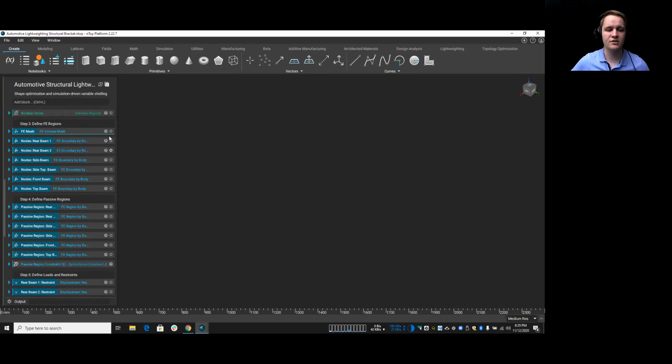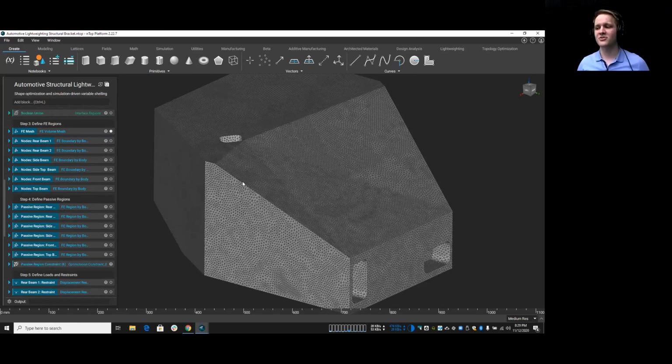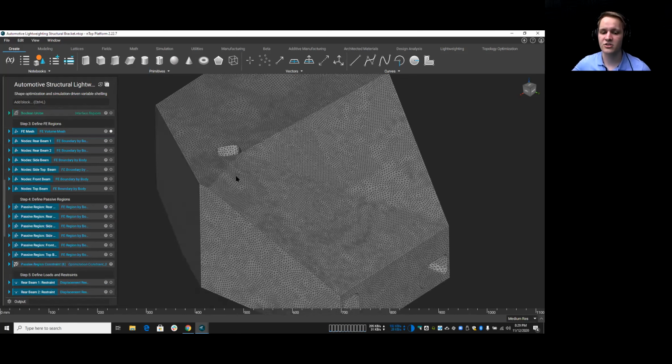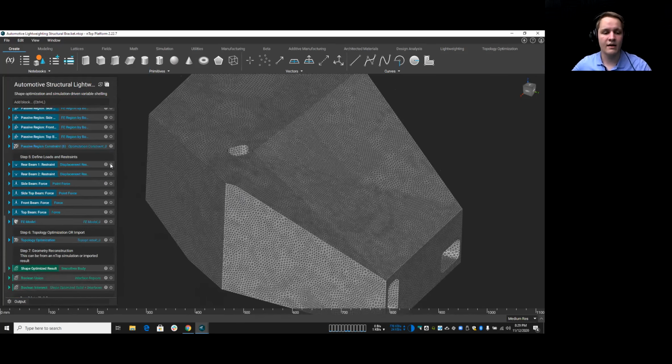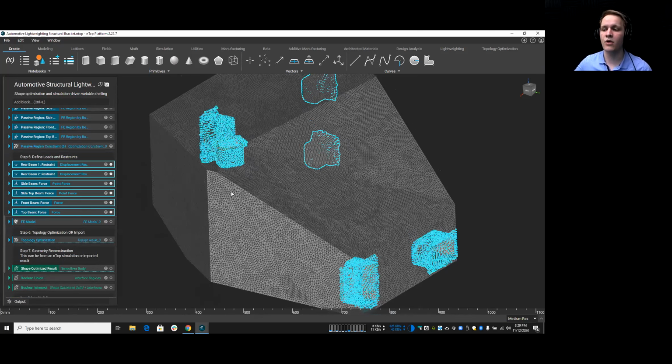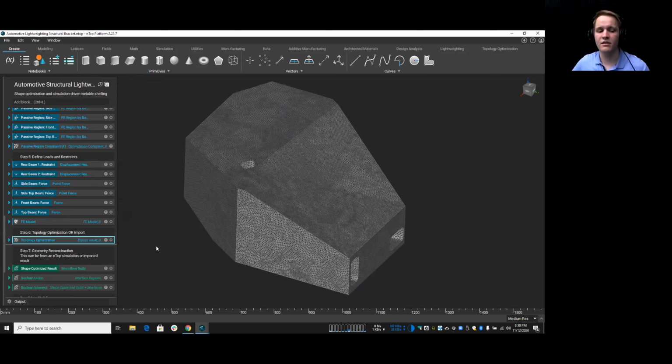Now, topology optimization, I'm going to assume you guys have some form of knowledge of it, but that's probably a bad assumption. So I'm going to briefly touch on a couple things. What we need to do is turn our design space into a mesh. It's a finite element process, so we have to mesh this part, and we then have to go through the process and apply boundary conditions to this mesh. So we need to load it, how this part is going to be loaded. We can have multiple load cases. We can optimize it to maximize the stiffness while reducing the mass. All of those sorts of things. All of the normal topology optimization stuff you can do here inside of nTop platform. But that's not the hard part.